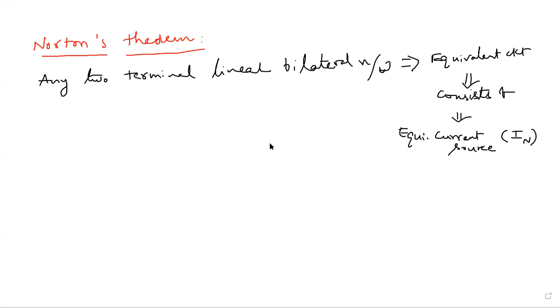But coming to Norton's theorem, in the place of the voltage source we are taking a current source. So for a current source, how will the resistance be connected? In parallel. Right, very good. Current source in parallel with the equivalent resistance. That resistance is called Norton's resistance, and sometimes we also call it Thevenin's resistance. Why it is called Thevenin's resistance I will explain later, but for now remember it is also called Norton's resistance, where Rn is Norton's resistance and In is Norton's current.